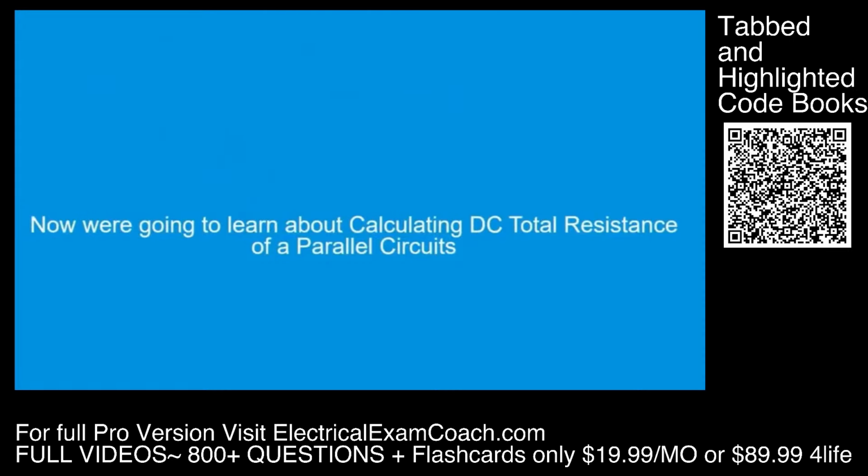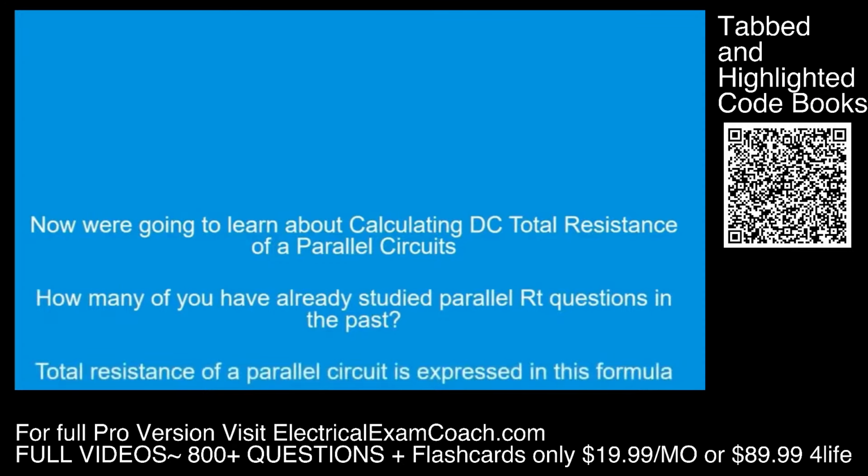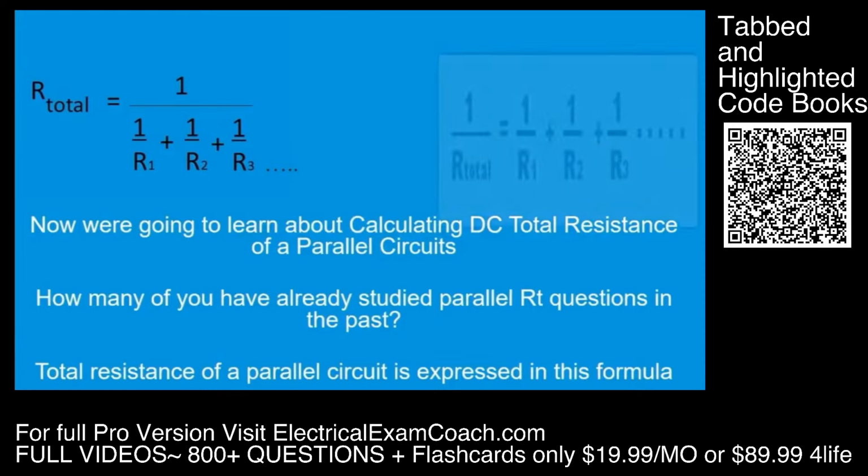Now we're going to learn about calculating DC total resistance of parallel circuits. We're also going to learn about calculating voltage drop across an individual resistor in a parallel circuit. How many of you have already studied parallel RT questions in the past? The total resistance of a parallel circuit is expressed in this formula. R total is equal to the reciprocal of R1 plus the reciprocal of R2 plus the reciprocal of R3, and so on and so forth. To get the reciprocal of a number, you will just divide that number up into 1. What we're going to do is first get the reciprocal of each resistor, then take the reciprocal of that number, and that is going to give us the resistance total.